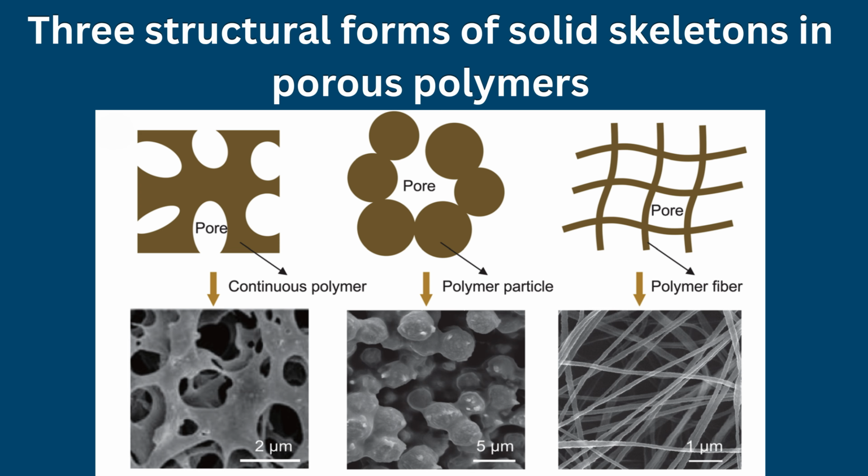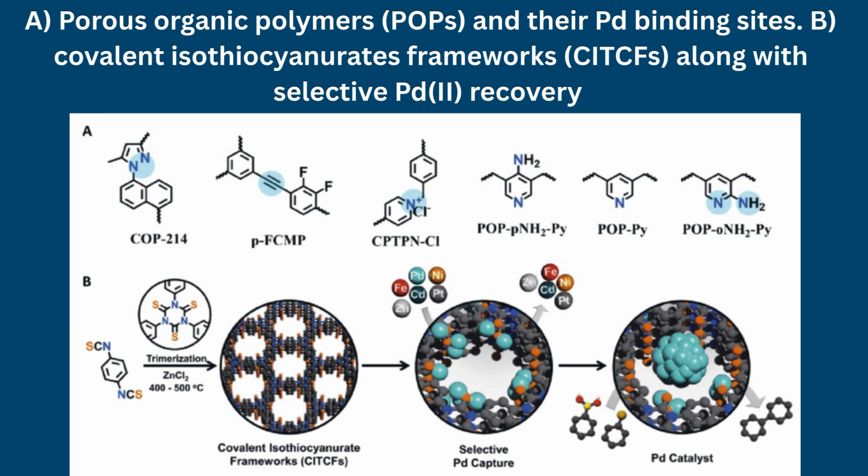In addition, hollow and coarse shell structures are frequently employed to enhance functionality in applications such as catalysis, thermal insulation, and controlled release systems. Surface chemistry also plays a crucial role in determining the performance of porous polymers. The presence of functional groups on pore surfaces enables a wide range of chemical modifications, allowing the introduction of specific interactions such as ion exchange, adsorption, or catalytic activity. These modifications can be achieved either through the incorporation of functional monomers during synthesis or via post-synthetic treatments. As a result, porous polymers can be tailored to exhibit highly specific and tunable physiochemical properties.